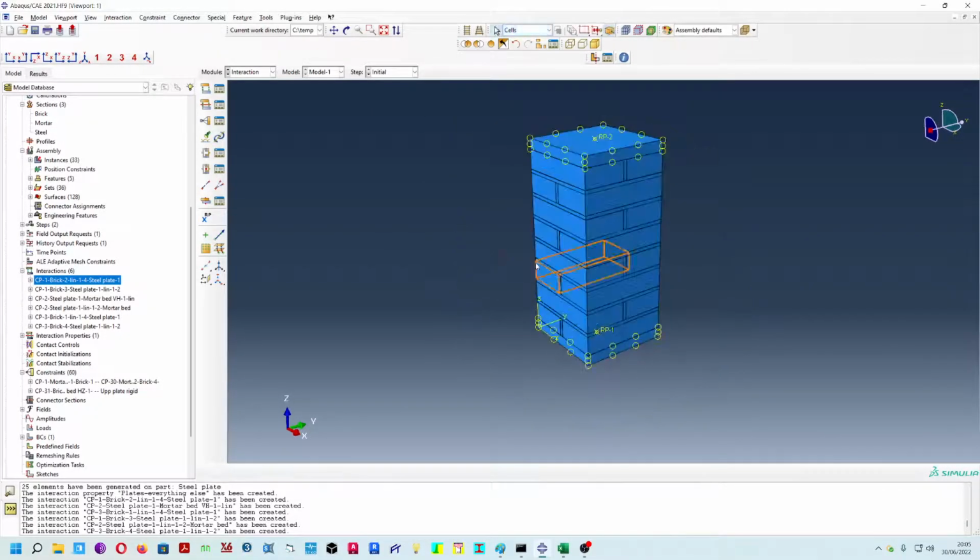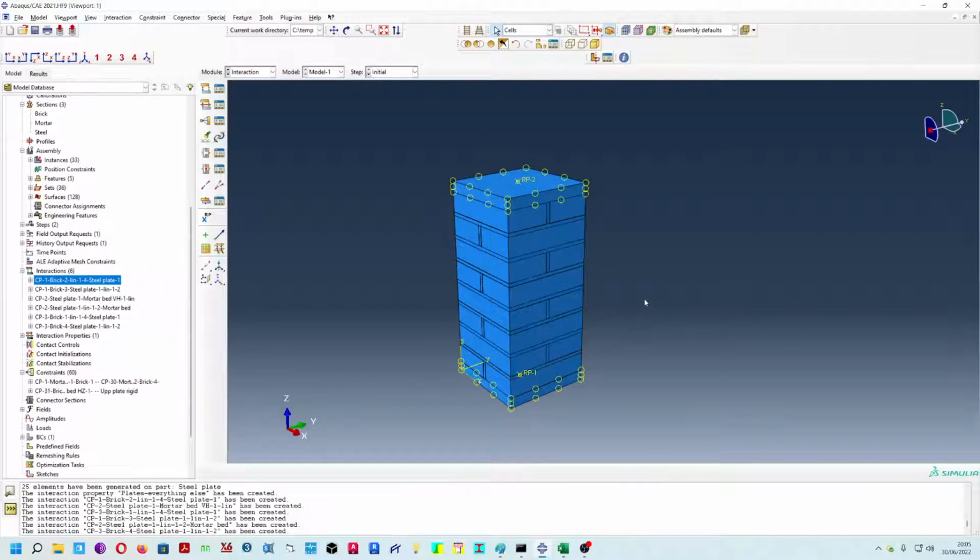good. We are missing now the load. I'm not going to use a force load. This is because the displacement-force function is not surjective, it's not bijective, and I really love to make displacement analysis according to a great book by M.J.N. Priestley, Displacement-Based Seismic Design of Structures, where he, Gian Michele Calvi and Kowalsky discuss how much better the displacement analysis is than the force-based one. So we're going to do a displacement control analysis.